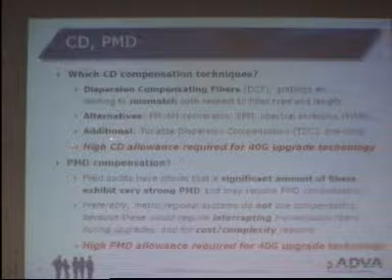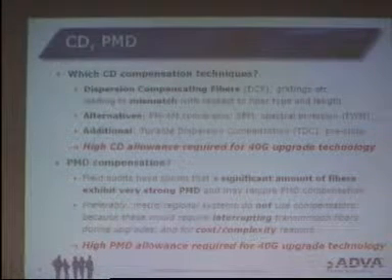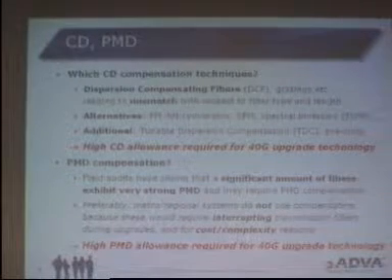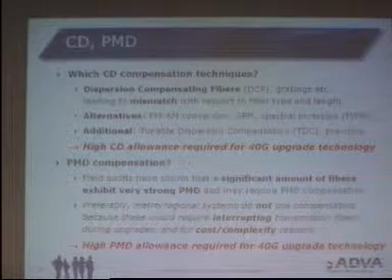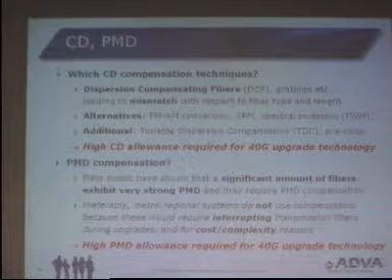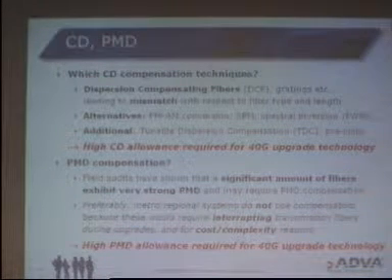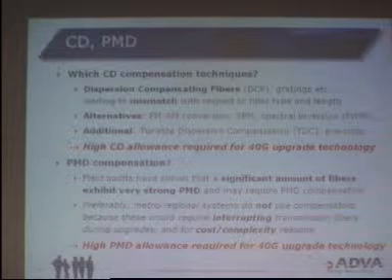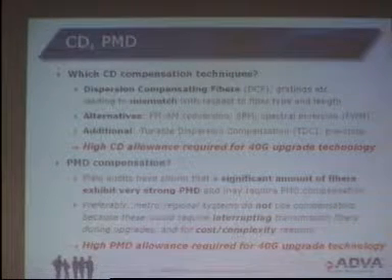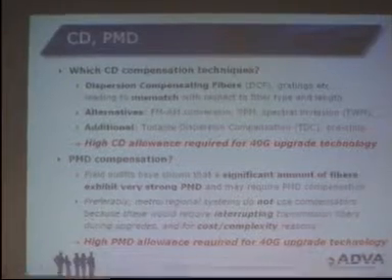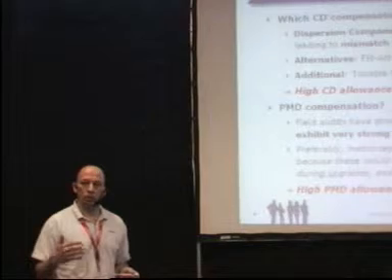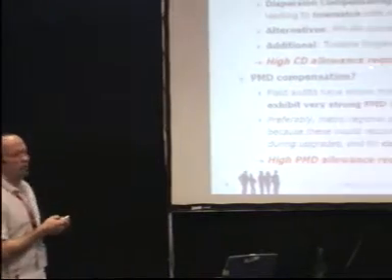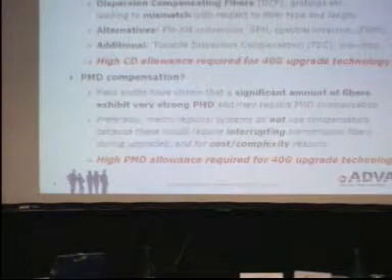With 40 gig, in addition to all the dispersion compensation techniques that are already in use, we have to use what is now called tunable dispersion compensation at the receive end. So hopefully we can try to make a 10 gig installation ready for 40 gig as well by placing tunable dispersion compensators in front of the 40 gig receivers. In effect, what is really needed for a stable and simple system, and simplicity is a requirement for Metro WDM, is a 40 gig technology which has highest possible allowance with respect to chromatic dispersion.